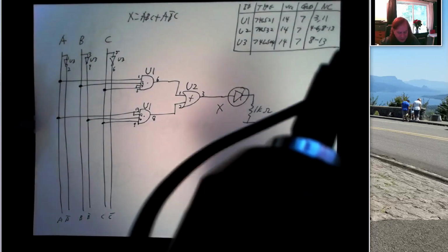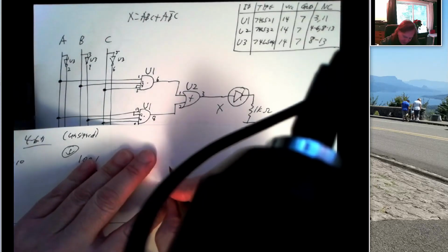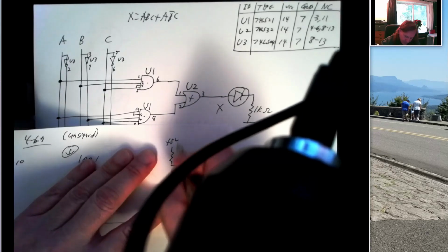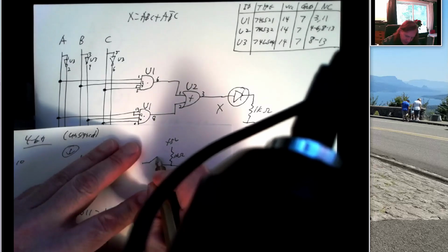All right, what about the input switches? So remember, there's a standard way we talked about wiring a switch, which is to take an input, pull it through a 1 kilo ohm resistor to 5 volts, and then use a switch.